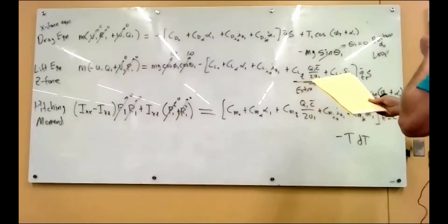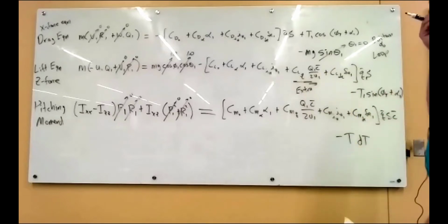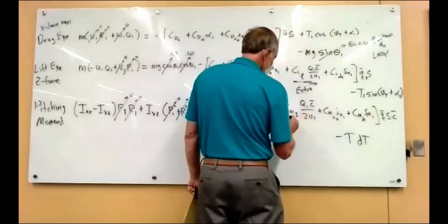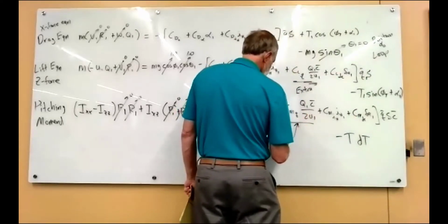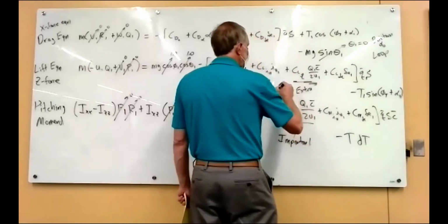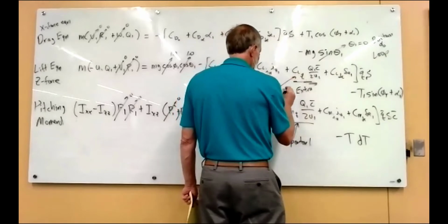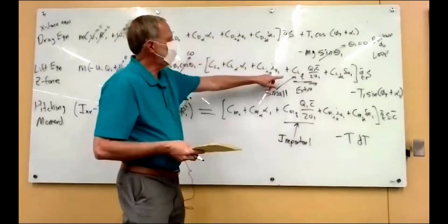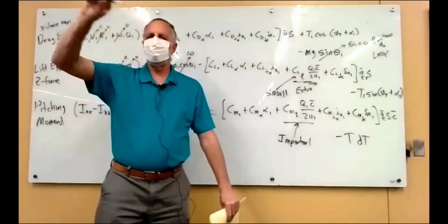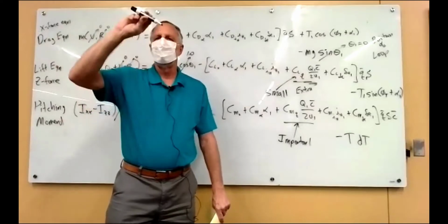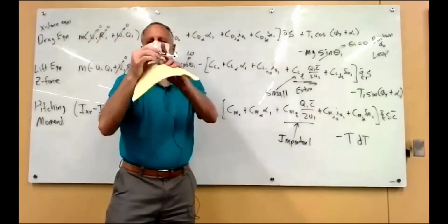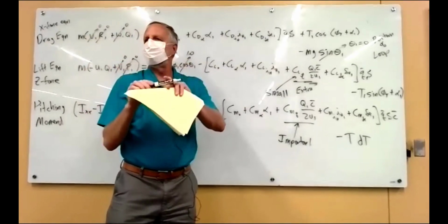Okay, so we've specialized these for the steady state pull-up condition. In the book, he says this term is important for the pull-up, but typically it is small. The effect here is that if the airplane has a pitch rate, the tail is moving downward, so you get some extra angle of attack on that tail.